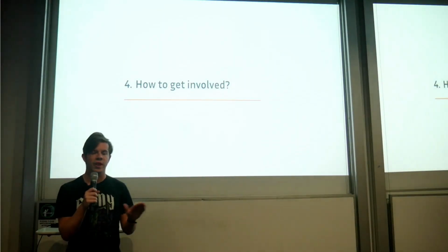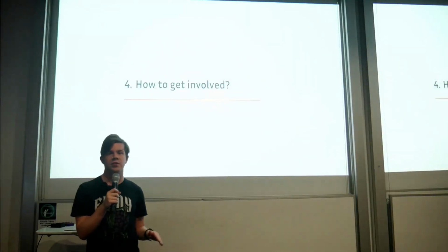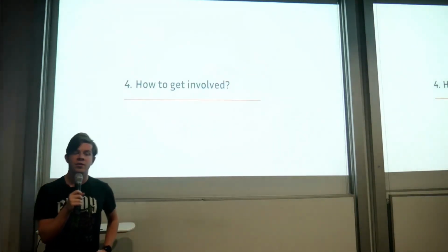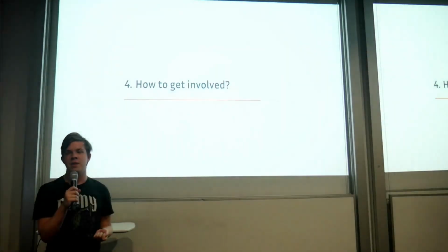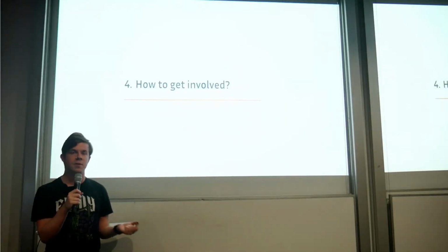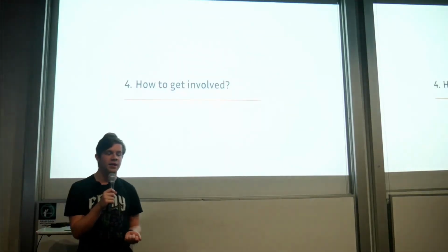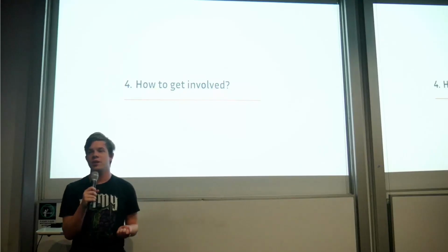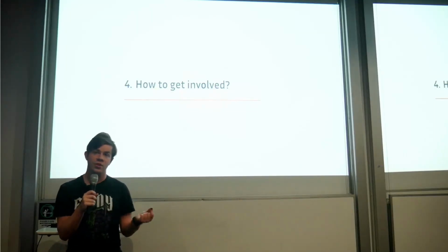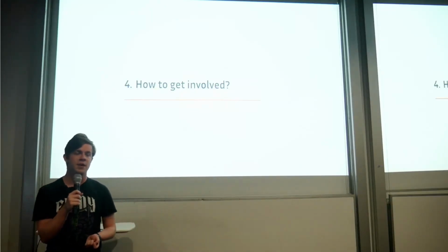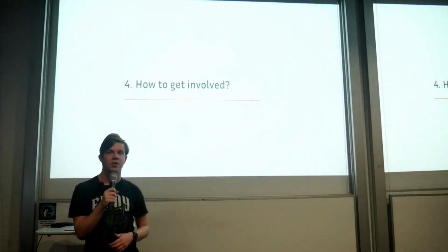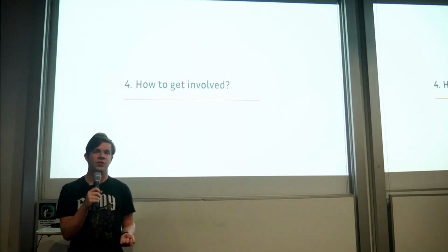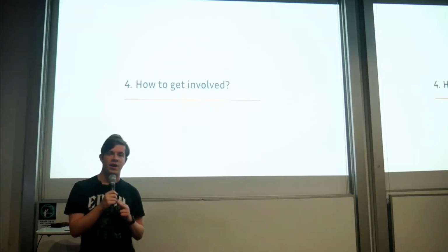The actual EMI stuff is less of an issue, but what is very important is the way that clocks are done. Things like clock domain crossing, where you have a clock go from one domain to another, is very bad. And of course, you need to minimize skew and jitter that we talked about in timing analysis. So the routing algorithms will have an estimate of the skew and jitter as part of their objective function, and they'll be able to help minimize that.